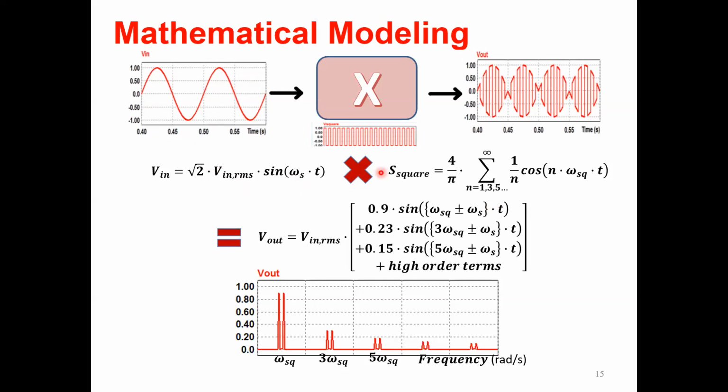Now, I always like to first think of it from a mathematical standpoint before actually going to a physical circuit. Once we know what the math does, the circuit actually just replicates that, and we just have to find a way to do it. Most circuits can do it, right? So let's say we multiply the sine wave with a square wave, plus 1 to minus 1. It's a typical square wave switching function. Then if you multiply instant by instant, you get a waveform something like this on the output.